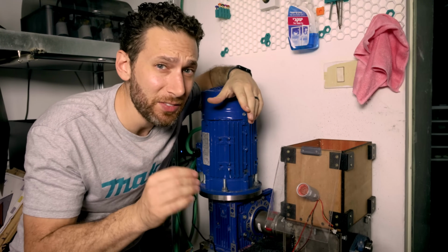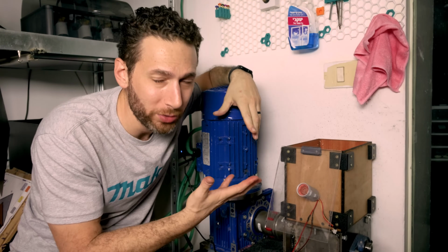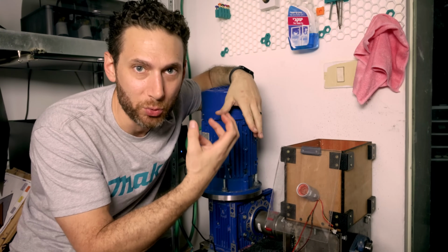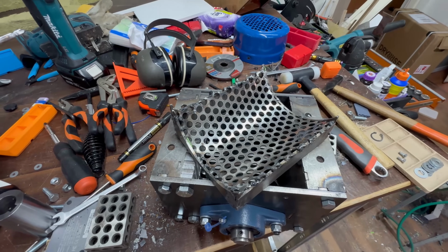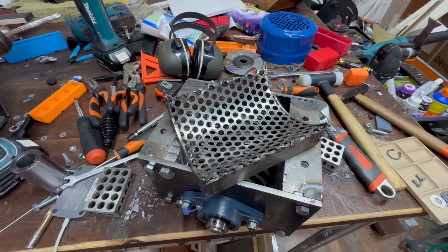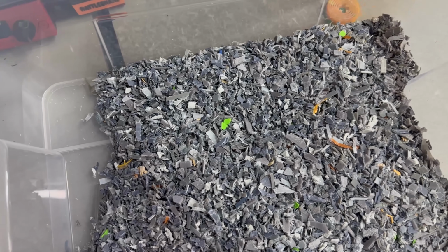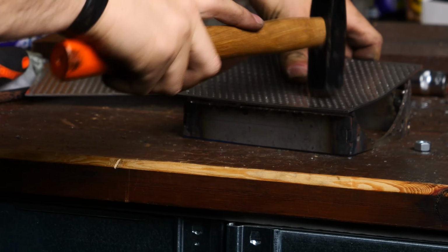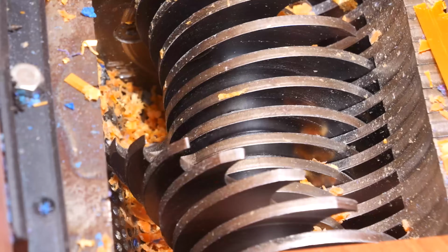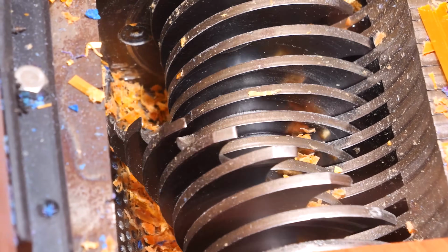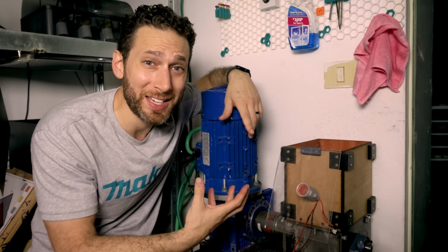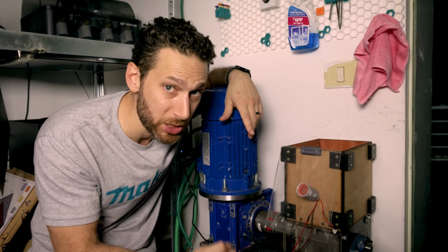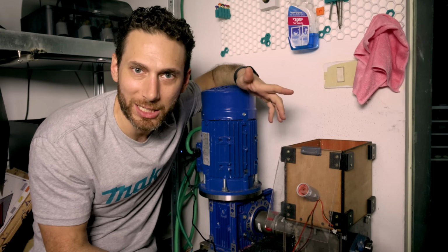And second, even when the shredder is relatively cold, the material just isn't going through the sieve fast enough. This shredder is designed to be used with 8mm holes, but those are way too big for my extruder setup. So you might recall that I swapped out the sieve with a 4.5mm one. Well, material keeps building up rather than actually going through the holes, which means that the heat also builds up in the material, which compounds my issues.